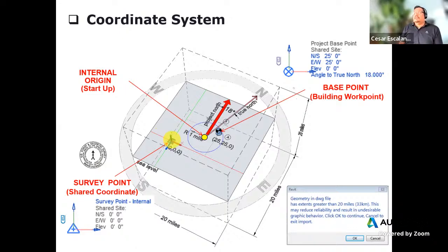Most of the civil surveys use state planes for point coordinates, and state planes have huge coordinates. We're talking about millions of feet, because the 0, 0 is way far away from the project. And so it's not possible to work with that level of numbers. For example, I think the 0, 0 of the California state plane is somewhere in the Farallon Islands, in the Pacific Ocean.